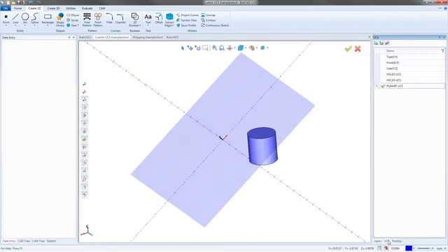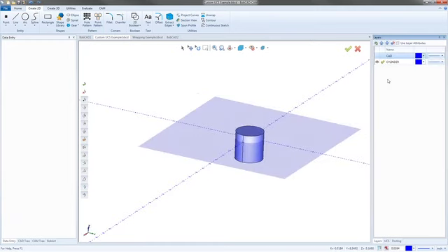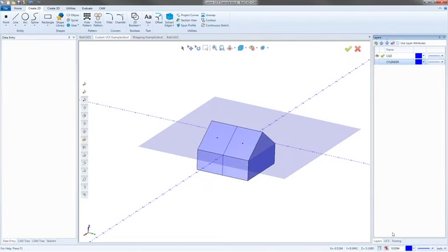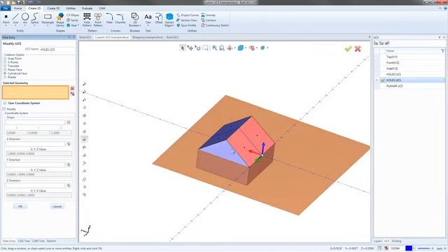So I'm going to go back over to my UCS. I'm just going to go to my holes one that I made, this little junky one. Turn this back on real fast. Turn this little guy back on. And then I'm going to go to this one that I didn't rename, and I'm just going to say modify. Now from the modify point, we can actually go in and rotate this. So the geometry right now is not going to be anything. We're going to say rotate.